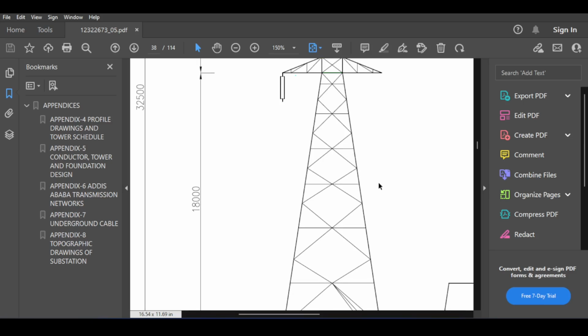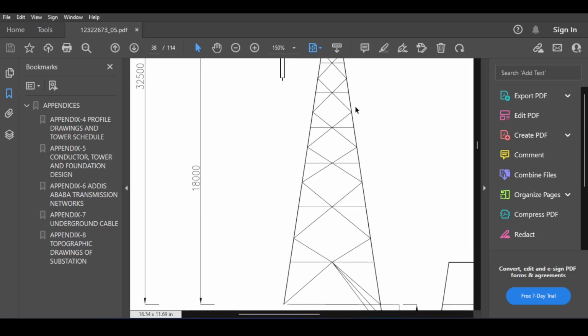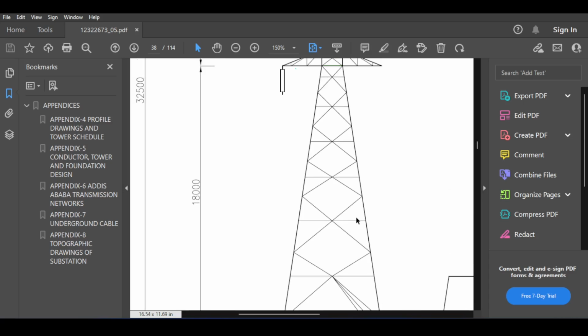So in that case, I would, for example, have 3 towers and check out one tower where I, for example, break this into 6 pieces. Another tower, I break this into 7 pieces. Another tower, I break this into 5 pieces and design all of those towers. Of course, the software allows you to design it very quickly and compare the weights and decide. So that's my approach. For now, I will not do a trial and error approach. I will just assume that I have seven spacings here, basically. So how do I do that?